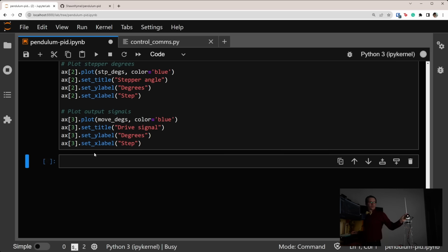Let's try adjusting it. So we're going to go up here. Let's move it to 0.1, and let's try again. Okay. So there weren't as many oscillations there, but you could see it struggling to keep up. And if we look at our plot, sure enough, it never quite reaches our set point, and it just kind of struggles to keep up. That means KP is too low. Let's try 0.5, about halfway in between. We'll run this again.